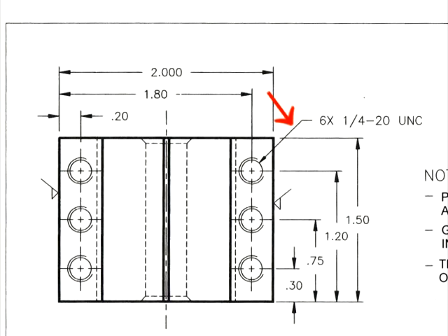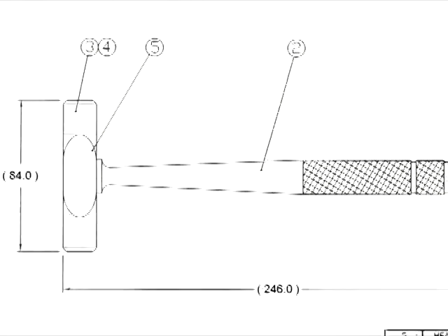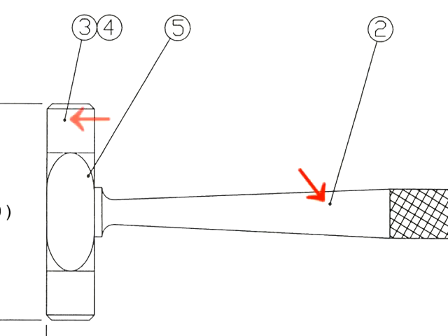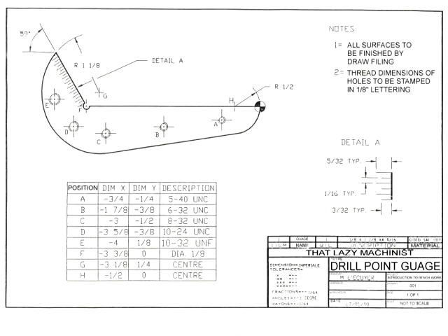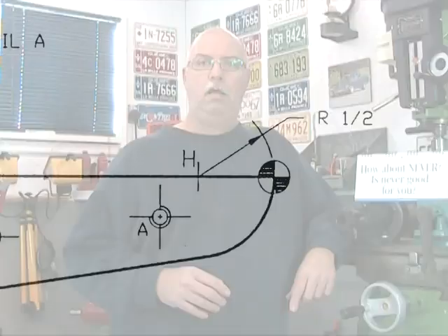But be careful. If the entity is represented by a line, well, the leader line ends with an arrowhead, as is the case here. But if the leader line points to a surface, well, then it ends with a point. And sometimes when dimensioning things such as arcs, well, the leader line's arrowhead can be positioned somewhere in the center of the line. Another thing that we can find on a blueprint are section views.